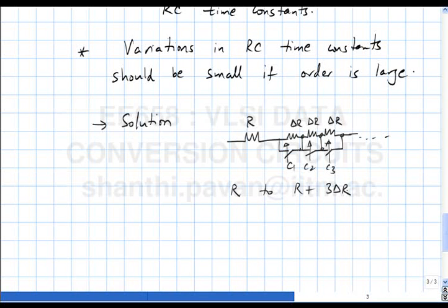You can see that you replace every resistor by some kind of digitally programmable resistor, where once you know what the actual R on the chip is, you can dial in a suitable correction code which will change the values of all resistors by the same factor. Is that clear? And this is not the only way of changing a resistor value. One other way could be to put conductances in parallel, or have some combination of series and parallel. So the idea is just illustrative.